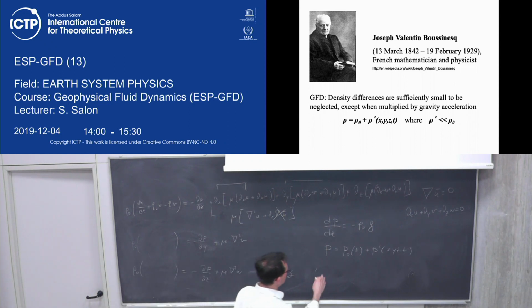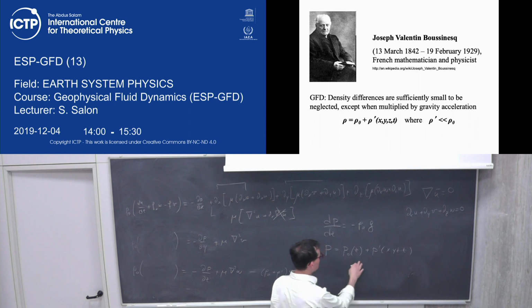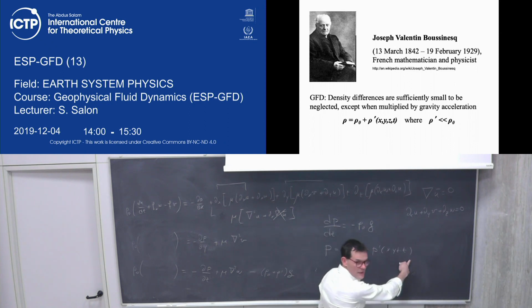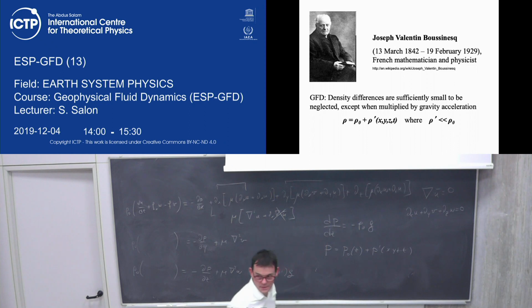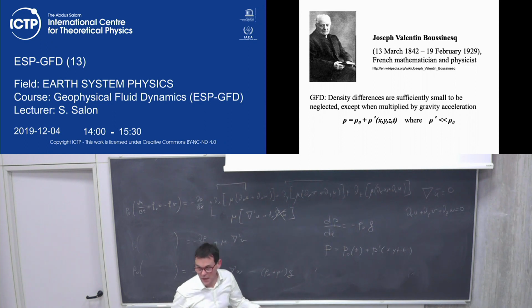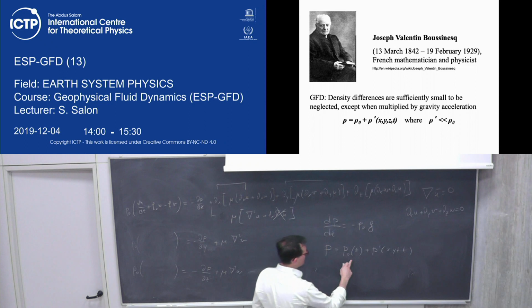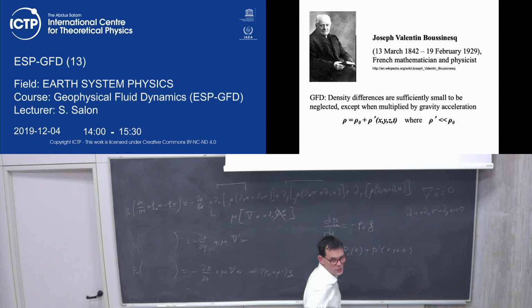So we can separate the effect of hydrostatic pressure from all the other effects which are not related to the hydrostatic. Okay, hydrostatic is static, so it's anything related only to the fact that any fluid has a weight, and so it exerts a pressure over the other, let's say, parcel of fluid which are above, below itself. So we can have the hydrostatic pressure, which is this one, and then the other one, which is the perturbation pressure, or also dynamic pressure. Okay?